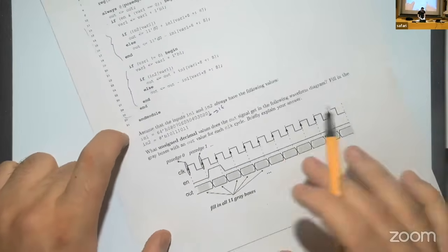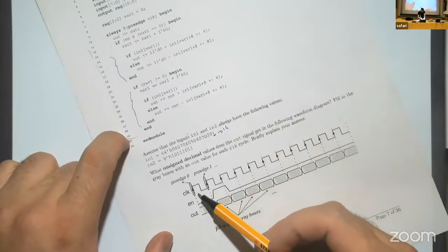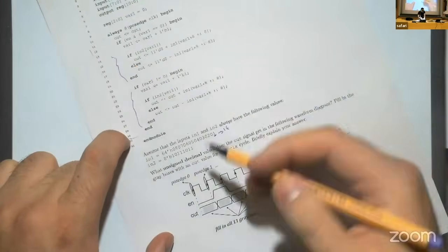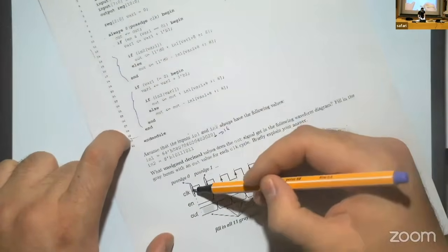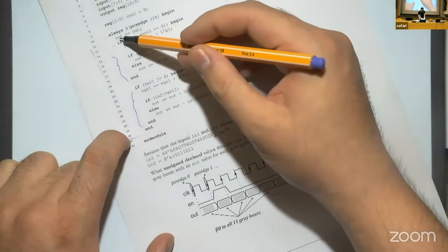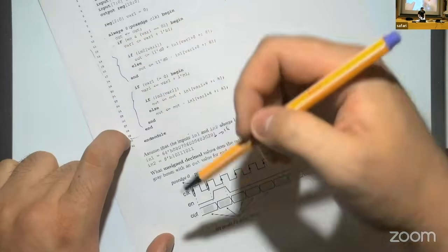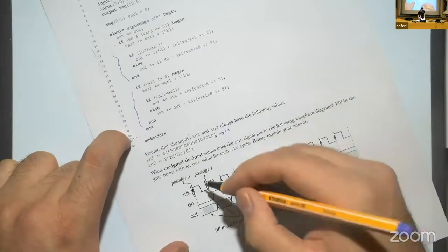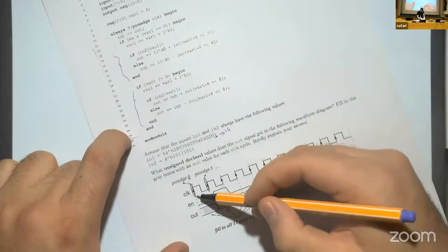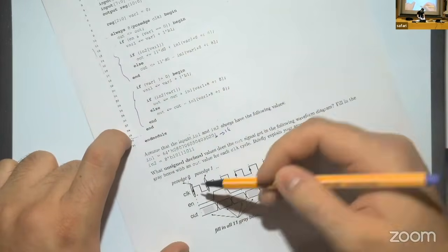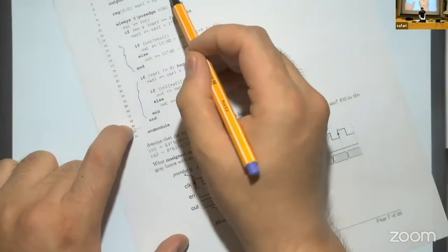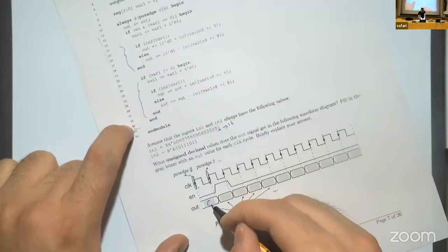Let's start. For the first one, we know that this is posedge clock, right? And this is the always block. When we start executing this block, the variables assigned in this block are updated at the end of the cycle, which means that this posedge clock 0 will be executed here, but the results are updated after this cycle. Here we know that the initial value is 0, right? So the out becomes 0.